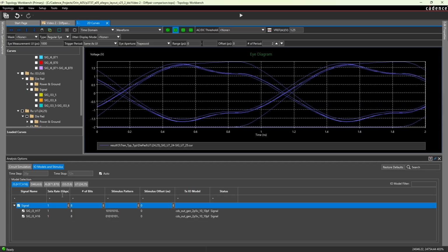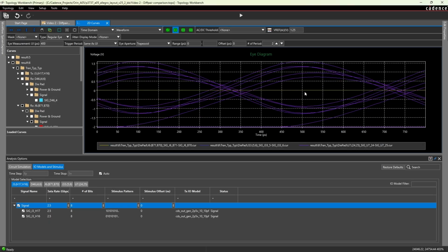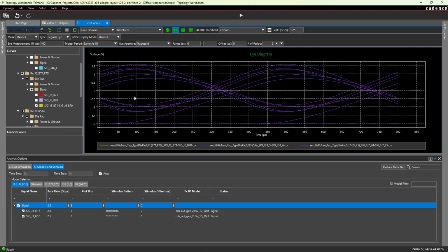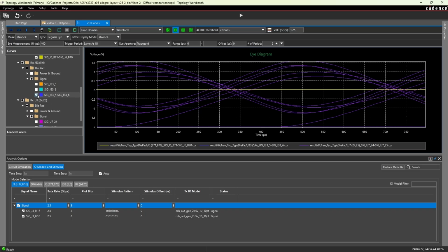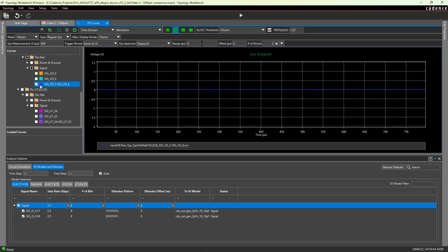Now, if we push this up, the connectors, not so much. If we push this up, obviously our connectors are not going to do as well. We'll rerun the simulation. Now, rerunning the simulation at 2.5 gigahertz, the eye diagram is a bit more closed, and this is what it looks like here. If we're still within the acceptable range, then this is fine. If not, then you need to double check and reroute your signal traces for the gigabits per second speed that you're looking for. Okay, so this is how you would evaluate your different traces and routing paths for different signal speeds and signals in general.